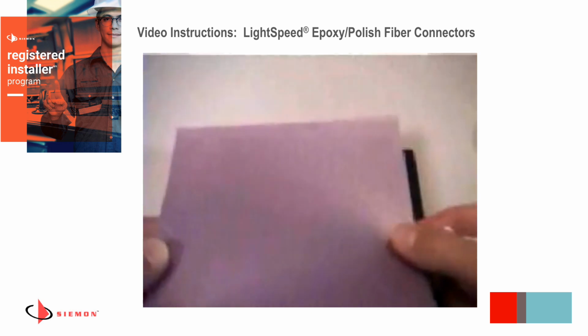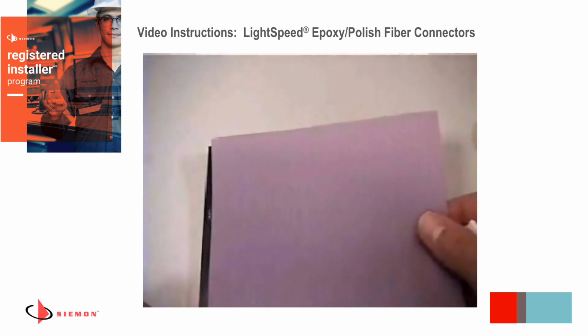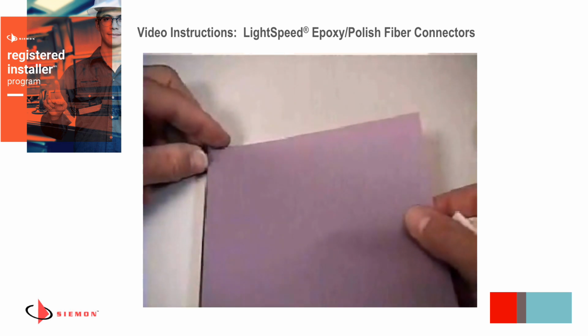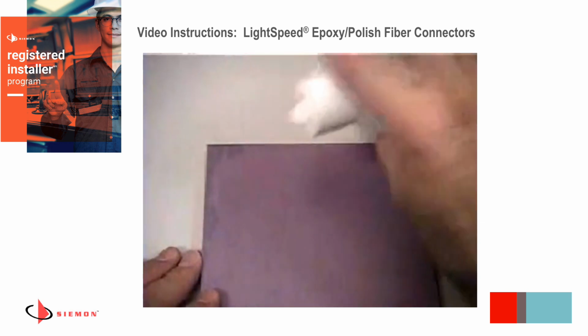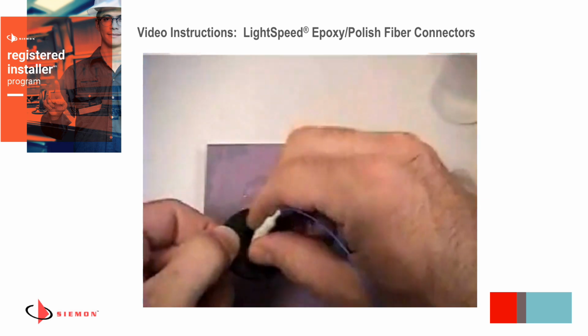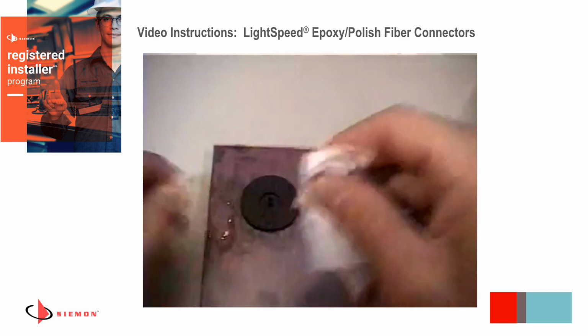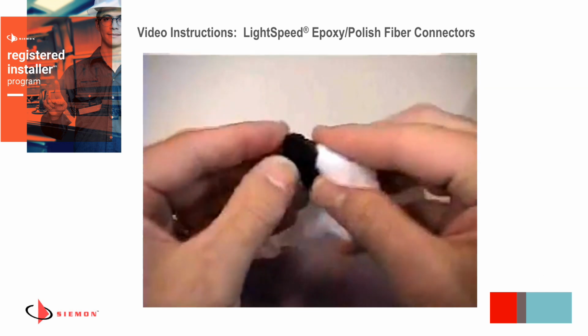Now replace the pink film with the purple 1-micron film. Prepare as done with the pink film. Glossy side of film down, remove any trapped air, add several drops of water, and continue polishing with medium pressure again for 25 to 30 revolutions. Again, remove the connector from the polishing puck and clean the ferrule, puck, and surface of film.